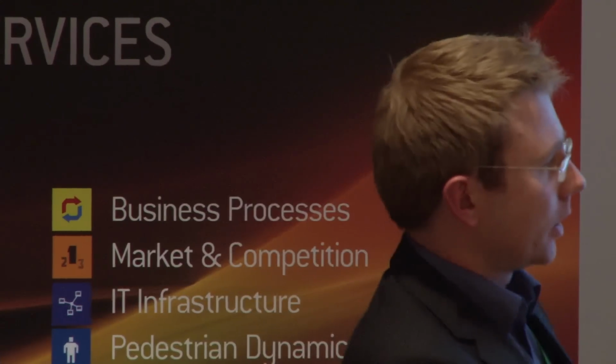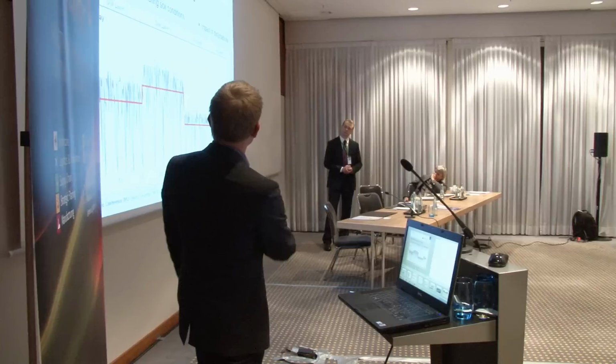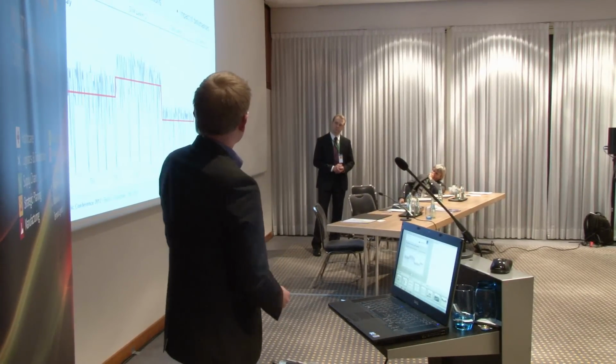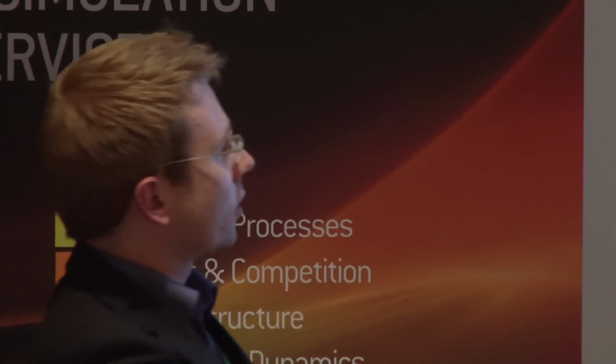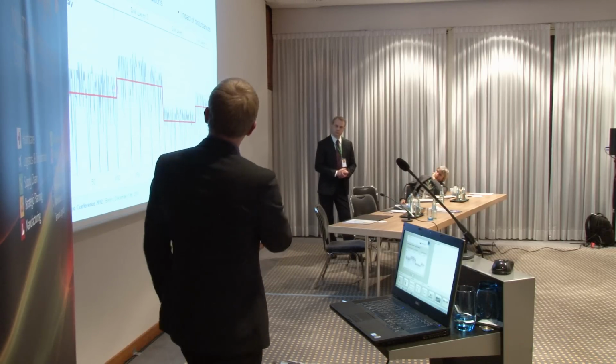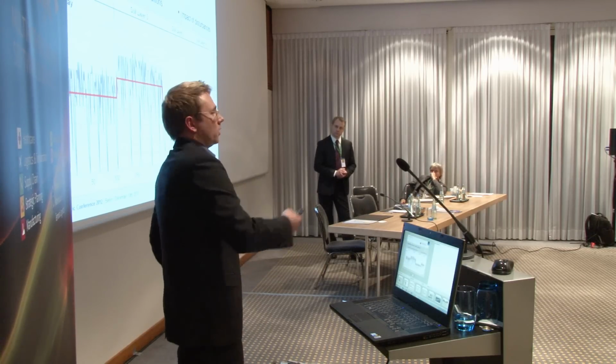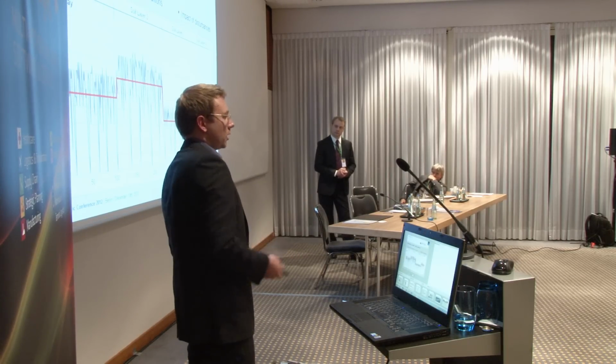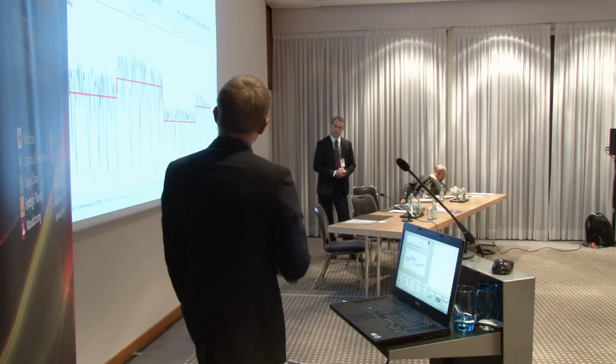Here on the x-axis you have the days, so this project took a little bit more than 1 year. You very clearly see the different soil layers. In the first soil layer you could excavate really fast, which means you have more time to build the rings. The second layer was even faster, so you could spend more time on the ring build itself.